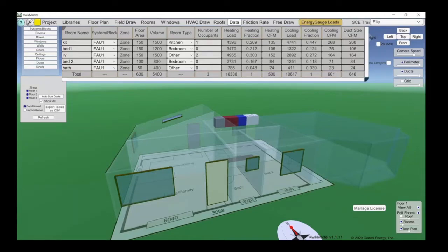The other thing is, if you have an actual hard copy of Manual J, you can open up a table and see what's happening when you pick a light wall versus a medium wall versus a dark wall, and say, well, that multiplier hardly changes at all. Why should I even worry about it? But of course, the easiest way is just to change it in the software, run it, write down the number, change it, run it, and see how big of a difference it makes. I really encourage you to do that frequently until you get comfortable knowing what's important and what's not.